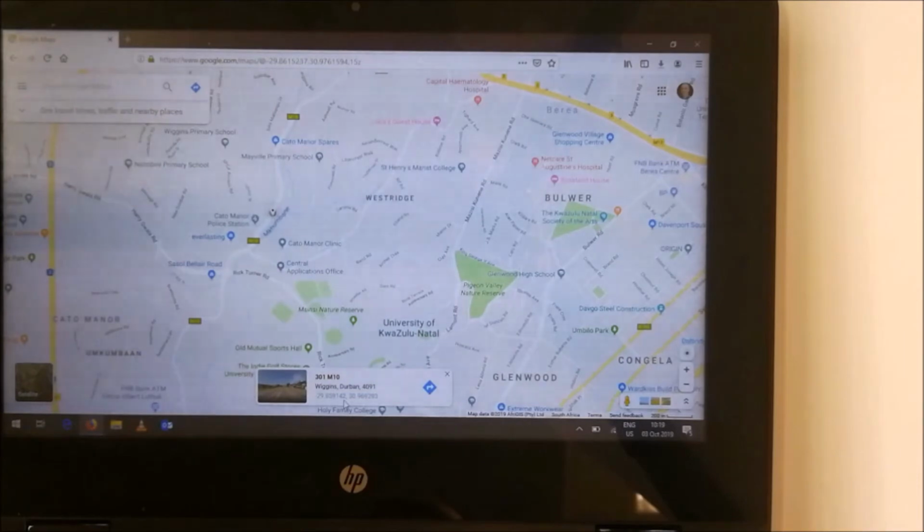And that would indicate that we are south, and south is referred to by the negative sign, while north would be the positive sign, and then 30.969293. And that's a positive value, which indicates that it should be so many degrees to the east, while west would be a negative value. So that is how latitude and longitude values are shown over there.